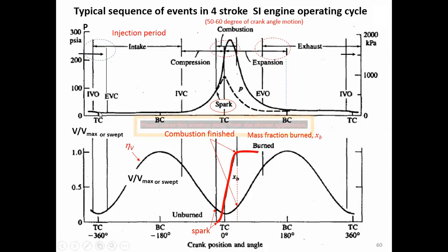Right? When the piston starts moving down from the top dead center, the exhaust valve closes. So that means what? During this period of time here, both the inlet valve and the exhaust valve are open, right? Because you see the inlet valve opens here. And when the inlet valve opens, it is the start of the intake stroke here.